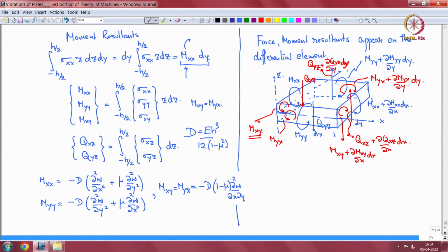For pure bending that is all we have. In line with Euler-Bernoulli and Kirchhoff theory, the rotational inertia is neglected, and therefore the moment equations are just static moment balances.